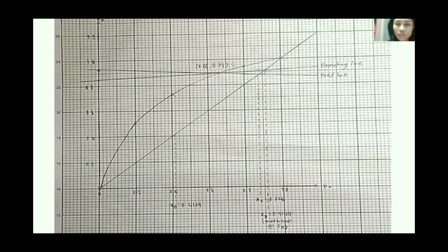To plot our equilibrium curve, plot all the trial and error values that we calculated previously, connect them with each other, and then we will get a curve like this. Starting from the origin, draw a 45-degree line. Plot the composition of the methanol in the feed stream, as well as the bottom and distillate streams on the x-axis. And then we take all these 3 points and draw three vertical lines until they touch the 45-degree line.